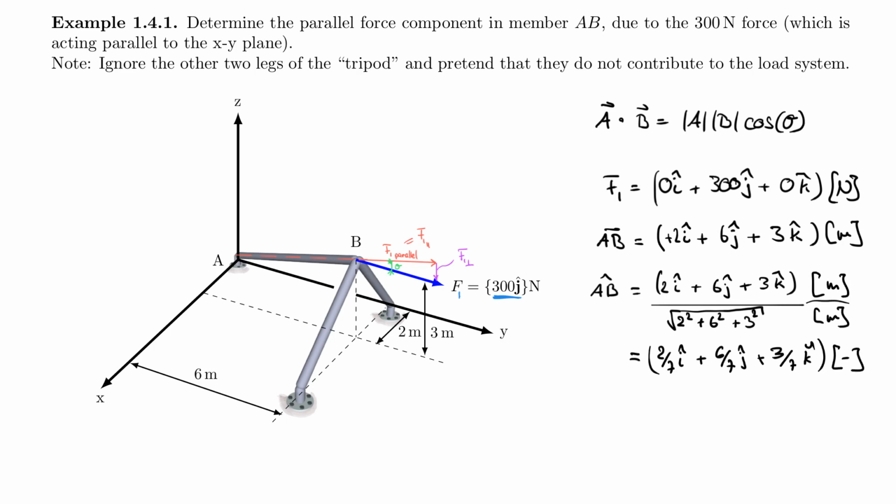And that is something that must be the case, otherwise it wouldn't work, right? So if you were to usually multiply this by this, so a force in newtons by a distance, then you would end up with what's later known as a moment, so newton meters, and that cannot be the case because we're really looking for a parallel force component. So you need to somehow get rid of the meter here, which is another reason why you have to turn the second vector into a unit vector.